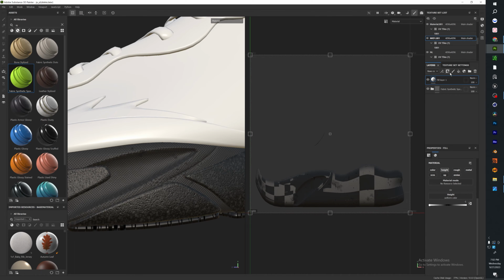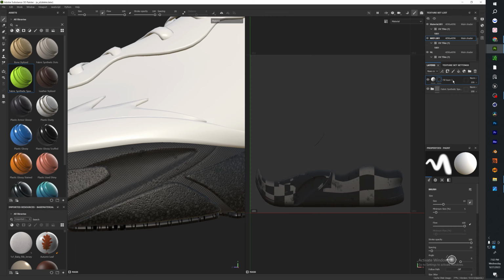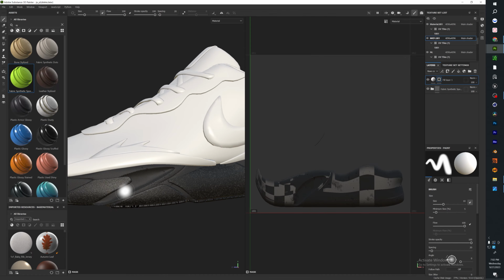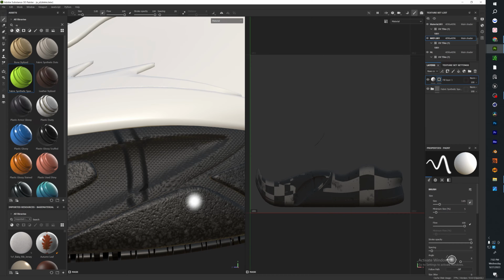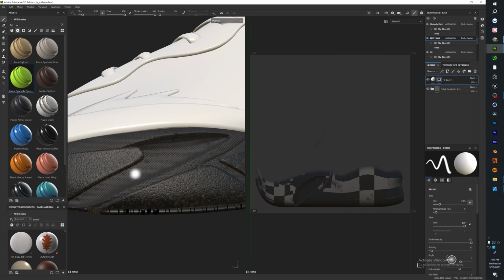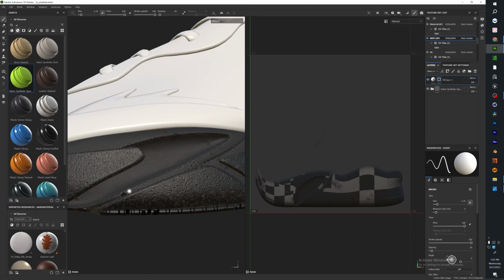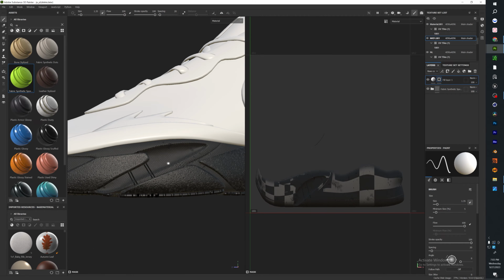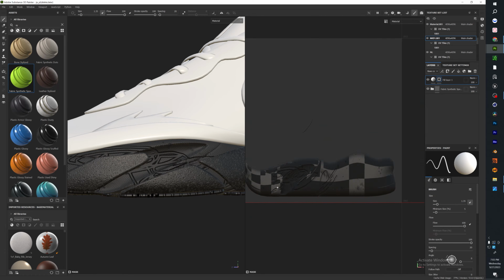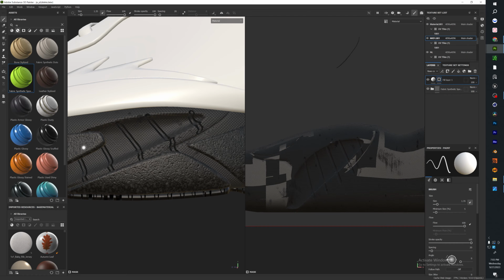So now that you have that set up, you want to add a black mask. Now while we're adding a black mask, everything that we paint in white is going to carve into the model. So you can either do this with a drawing pad, or you can do it with your mouse. A cool trick that you can use, if you click and hold down shift, you'll get this little dotted lines, and that will make your lines perfect. Not only can you texture on the actual 3D, you can actually texture over here in the 2D, whichever one works easier for you. Beautiful thing about using the mask, all you have to do is hit X for black and just clean it up.